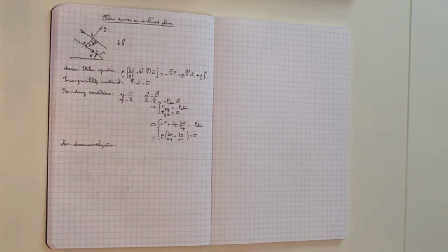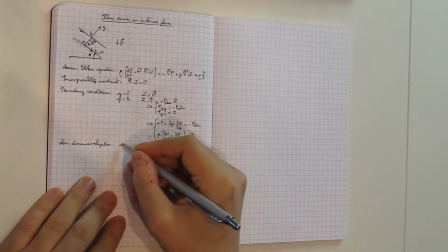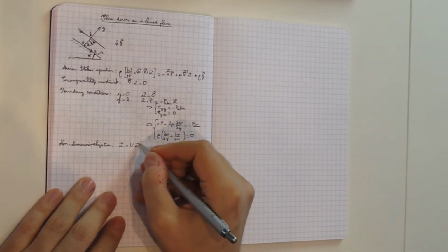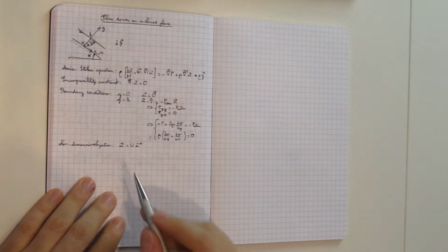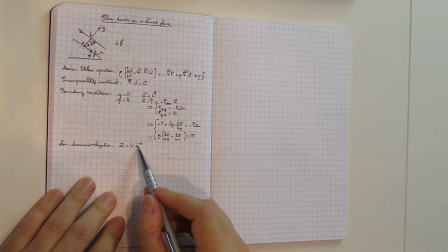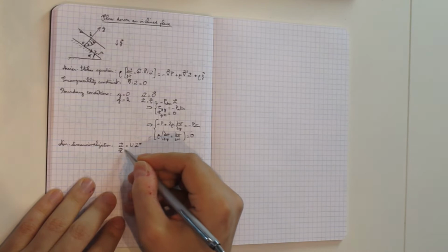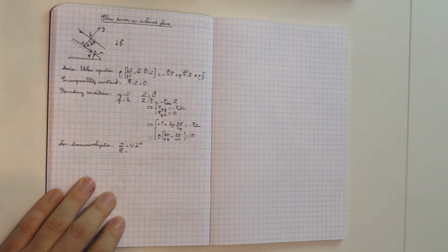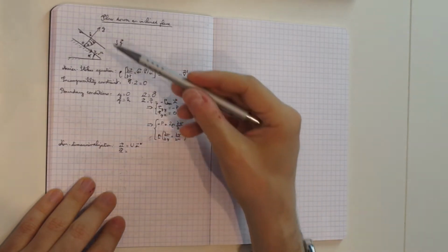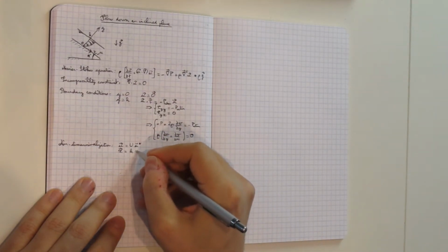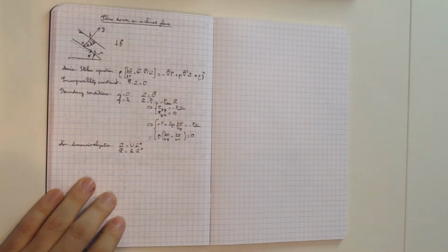Starting with writing down the scaling quantities. For the velocity, we are just going to use a velocity scale capital U to non-dimensionalize our velocity. This is the dimensional velocity, this is the non-dimensional velocity scaled on capital U. For the positions, the only scale that we know in distances here is h, the height of fluid. So we're going to scale everything with h.